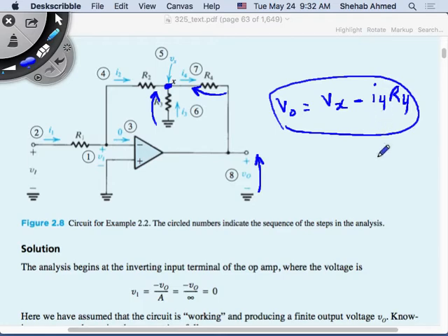The trick was we were able to increase I4 without increasing I1. Because if you increase I1, what does it mean? If you put a voltage, you have a small resistance and high current will flow, which means that the input impedance of the amplifier is small. But I kept this whatever I wanted it to be, a large value. So I kept this large, but I was able to amplify the I4 going through R4 by using this trick.